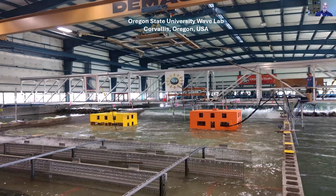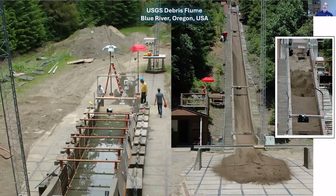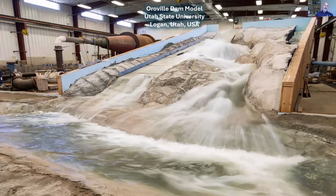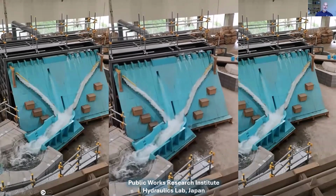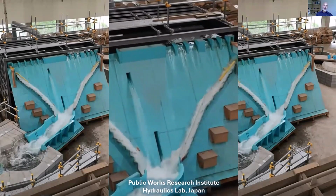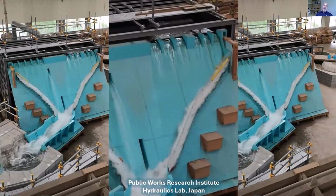You can do, I had a model that worked exceptionally well where we got the plan form. We were able to characterize the sediment movement on the plan form. And in that we used a really lightweight plastic and allowed it to shape. So what it's doing is the beach is responding to the action of the wave. Okay, so that, you know, the energy profile of the wave. And then after the structure was put in, I went back and I had a look and I reprofiled it and it worked. It was almost spot on. So it is possible, but it's often just very particular scenarios and can be really challenging.